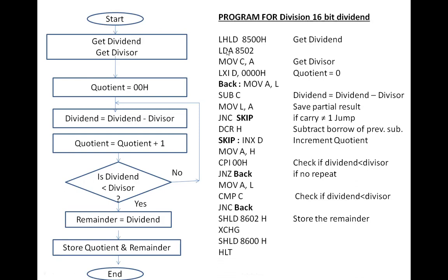And then it is going to halt. So in this way, this 16-bit division can be obtained with the help of an 8-bit divisor. Of course, we have to do some processing in between, because the time will come when the value of the lower order dividend will become less than the value of the divisor, and it has to take the borrow.